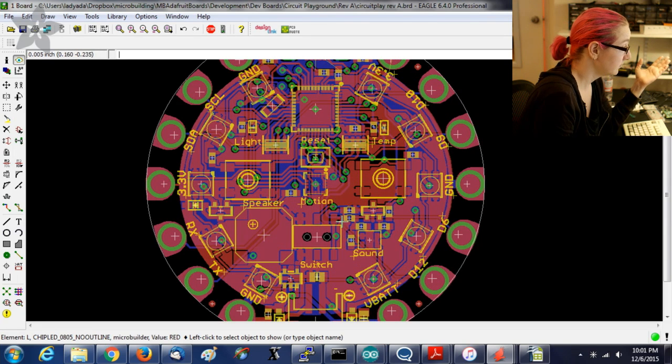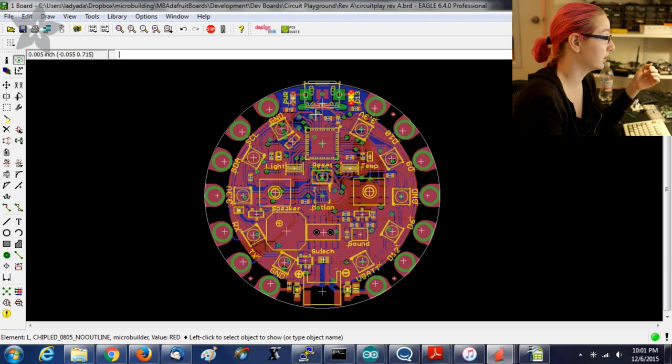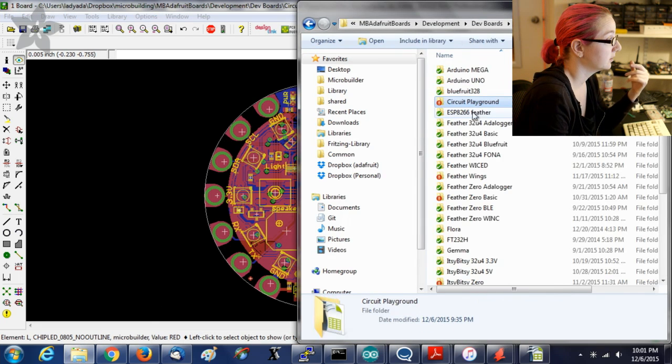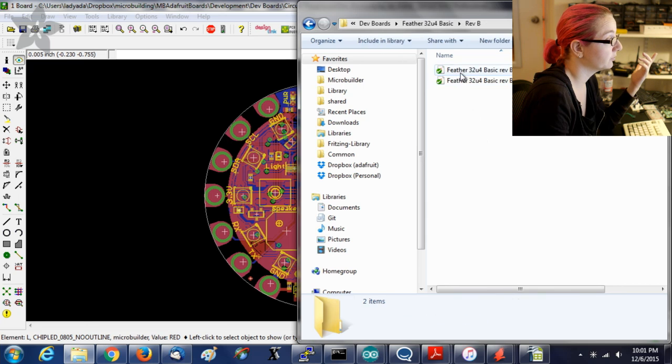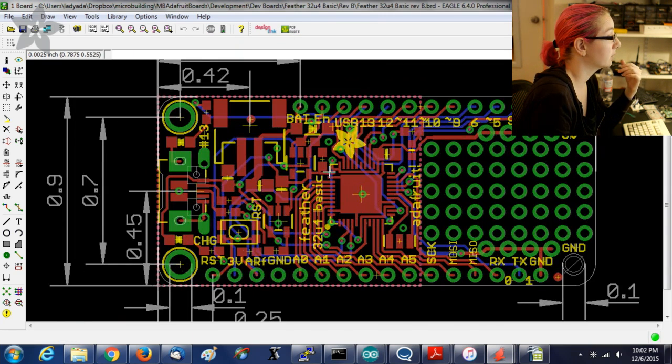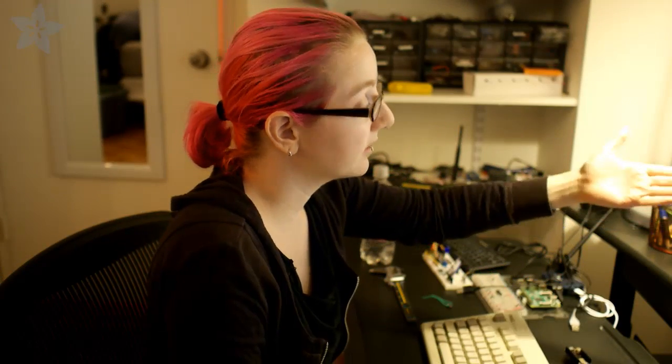Normally I would just stop with, okay, I got the USB. If you look at, for example, the Feather 32u4, which is kind of what this is based on, you've got your microcontroller over here, your regulator, a power supply, JST, micro USB, same deal. A Schottky diode. It has a little battery recharger and a reset button. But basically it's the same thing.